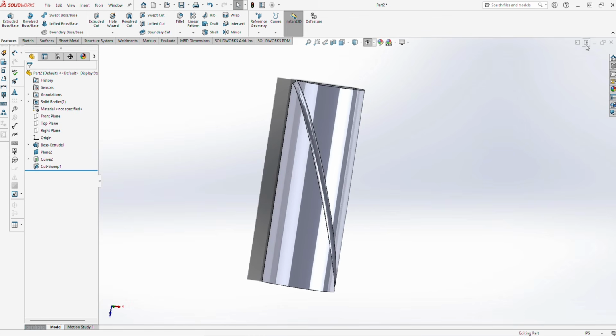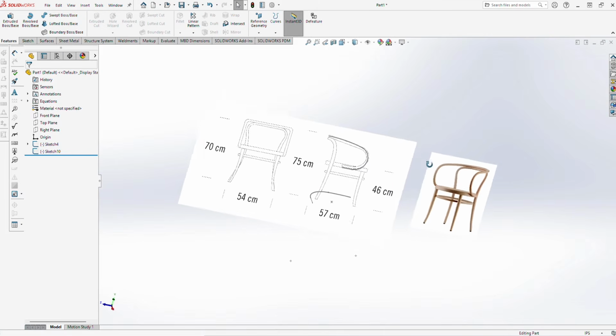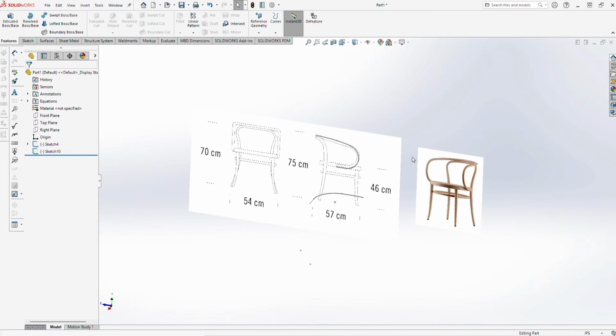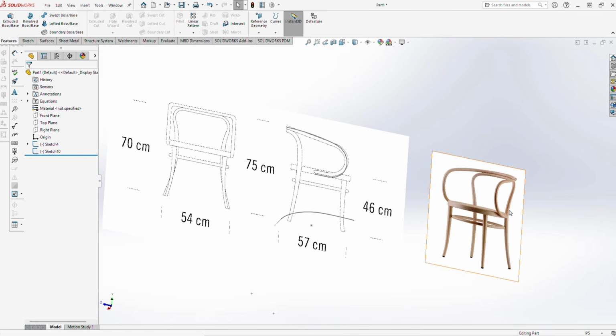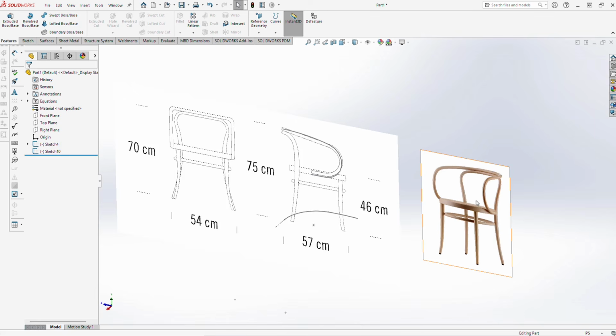Let's take a look at projecting a sketch onto a sketch. What projecting a sketch onto a sketch does is combine the two input geometries into a 3D curve. It will take sketches from two orientations and generate a curve that fits both of those sketches in each orientation. In this example, we're trying to model the armrest for this chair, and as you can see, it's pretty curvy in multiple directions. That might be hard to generate a sketch for if we didn't use this technique.